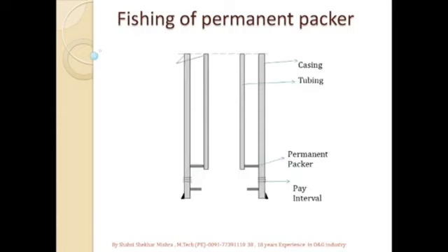Here is a simple diagram of a well with a packer completion. So here the permanent packer is there above the perforation interval, and normally we put an SSD above the packer for well killing or displacement or any other operation.